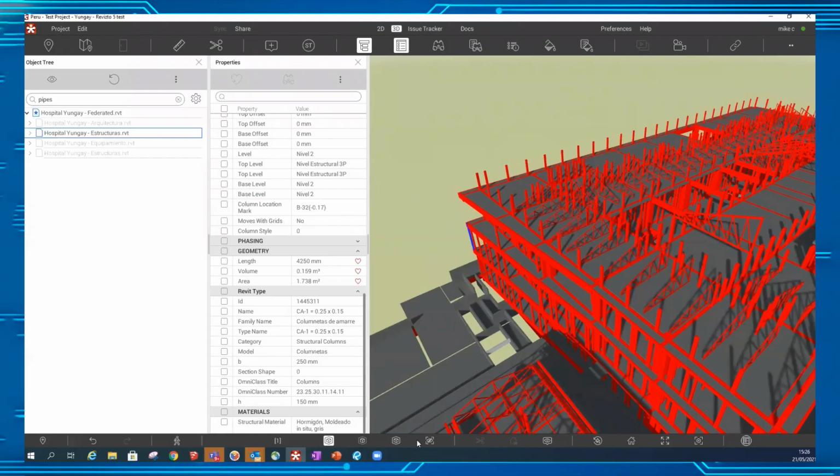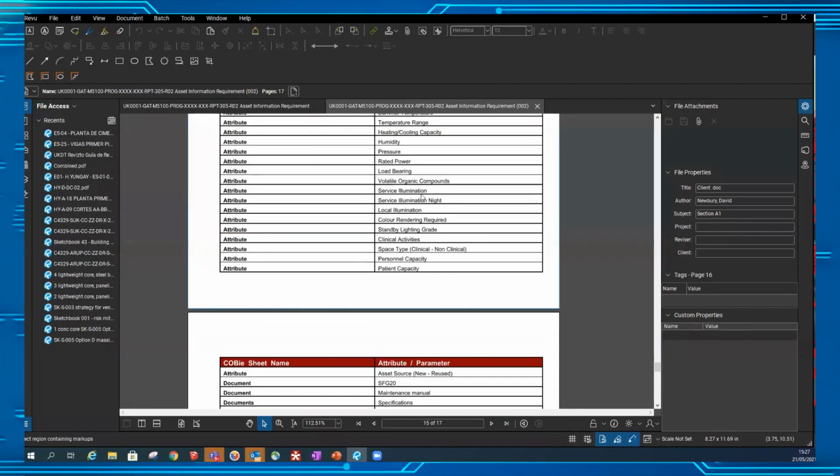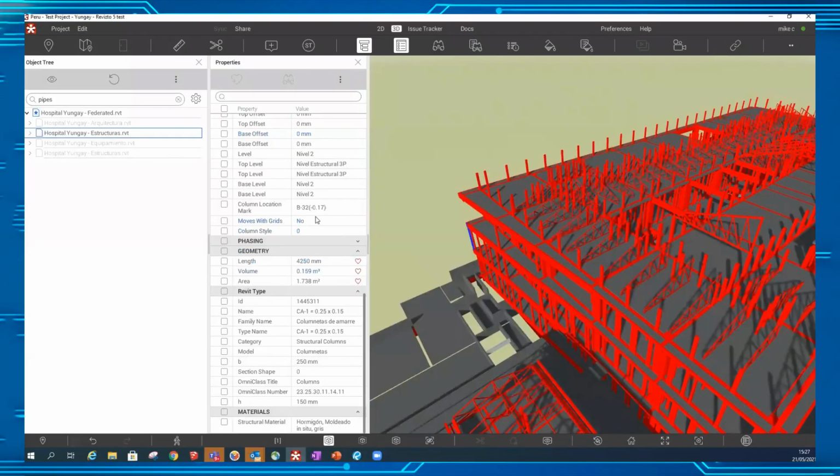And that's why, similarly, some of these attributes that are unusual or specific client requirements won't necessarily be included automatically, so the contractors will need to add them in. So looking for those and flagging up to the contractor early that those parameters need to be there is important. I've certainly made that comment in looking at some of the BIM execution plans that we've received. We've pointed the contractors to that document to say, please don't forget to include these attributes.